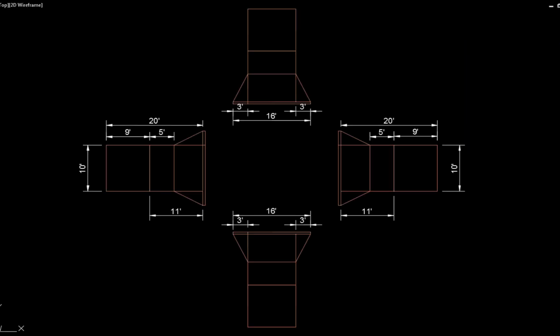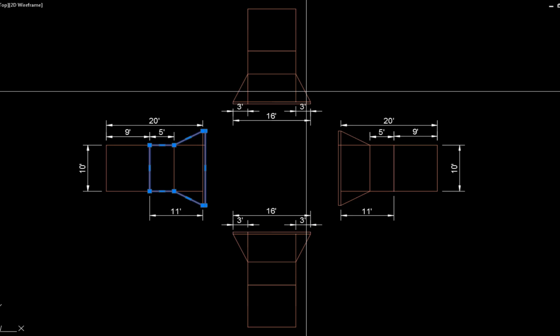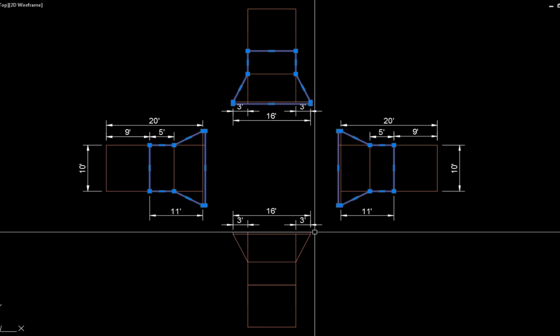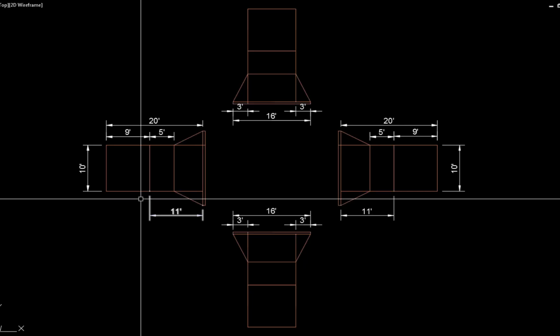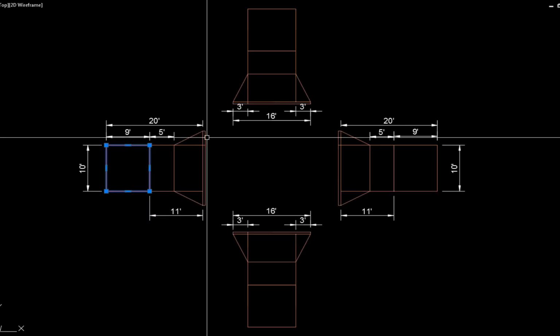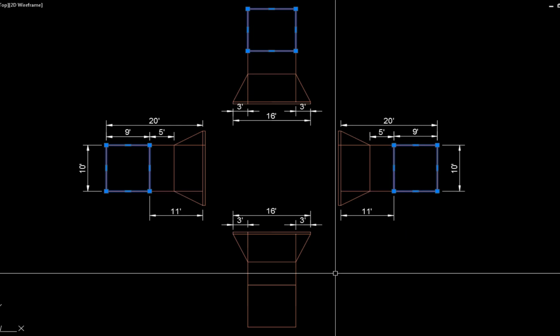Each driveway plan template contains a flared dustpan-shaped approach section between the curb and sidewalk and a driveway section beyond the sidewalk. The driveway approach and sidewalk sections are a closed polyline, and the driveway sections beyond the sidewalk are also a separate closed polyline.